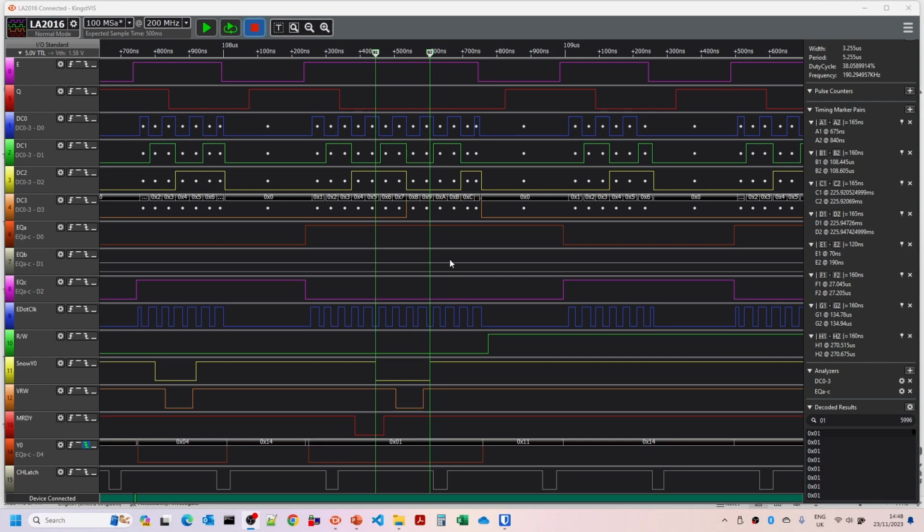Okay, after wiring in the MRDY circuit, what I have done then is a round of fixes and things, which I'll summarise in a minute. But just to show you, this is a trace from the most recent run. You can see here the normal E clock signal is high. If you look on the right hand side over here, you should be able to see it's about 260 nanoseconds, and the full cycle is 500 nanoseconds, so that's about 2 megahertz, because we've got the system clock running at 8 megahertz and it divides it by 4 for the 6809.